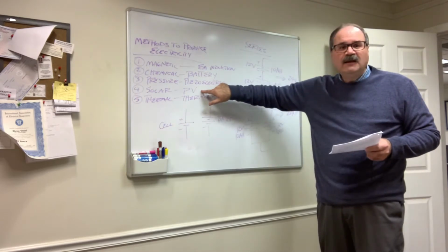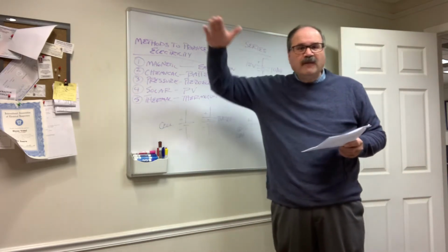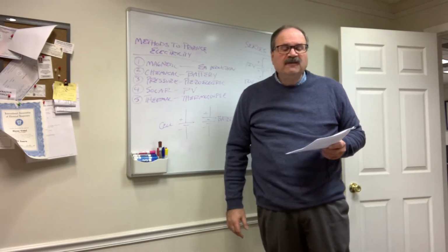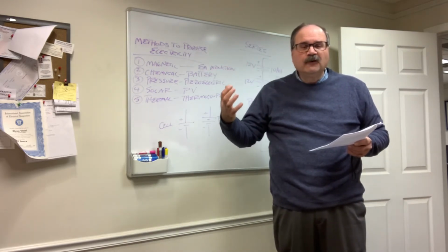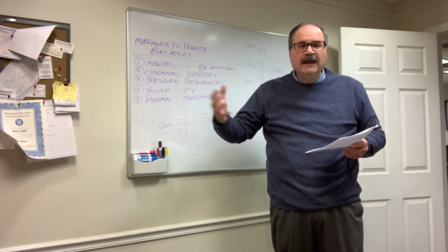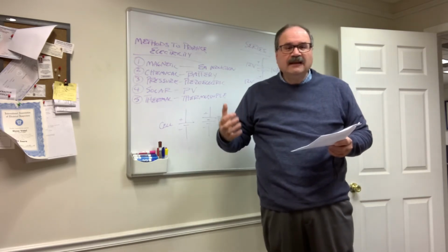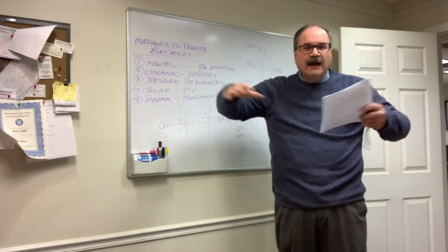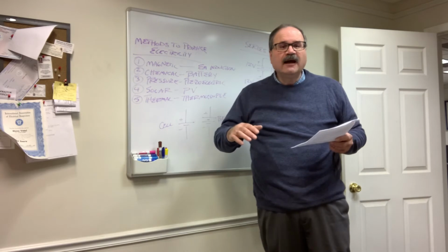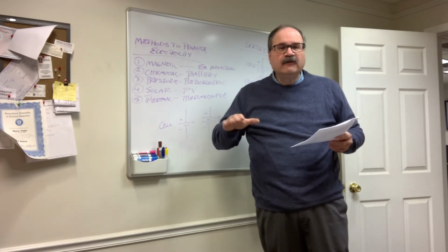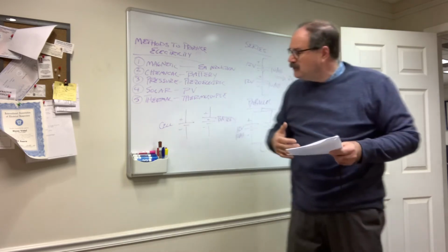Solar, the most common method is photovoltaic, and a very popular topic these days. If you drive around, you may see solar PV cells on roofs. What ends up happening: photons from the sun are absorbed by a solar cell in the solar PV array. Those photons are converted into electrons, and it actually produces DC or direct current, and then all of the solar PV cells that are tied together are fed into what's called an inverter, and the inverter converts the incoming DC voltage into an AC or alternating current voltage for use.